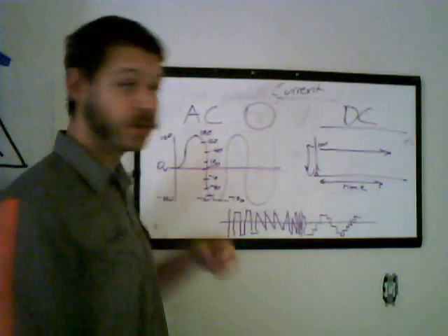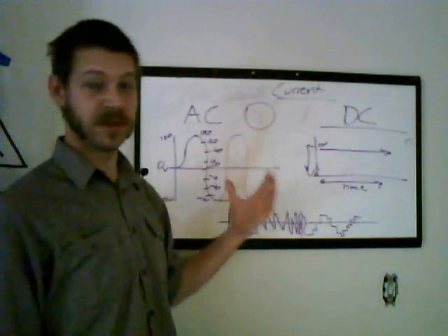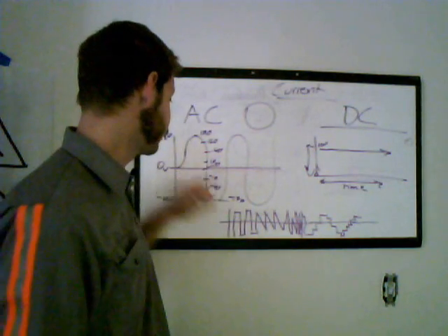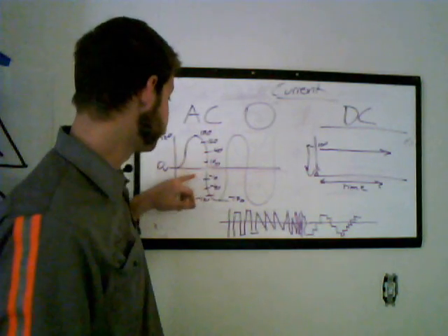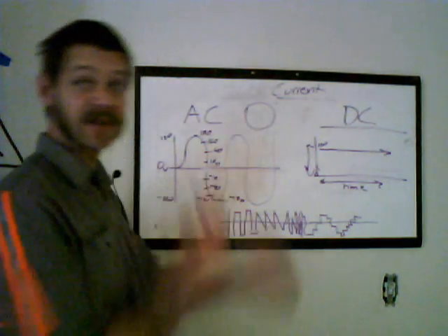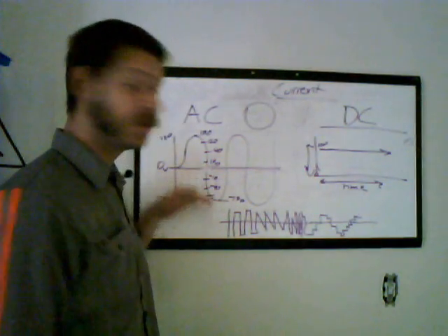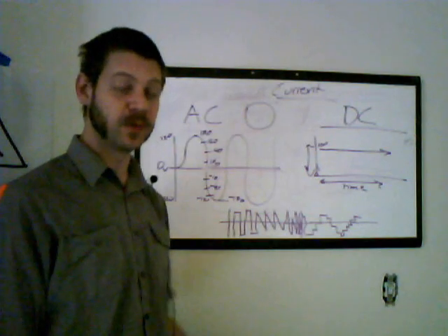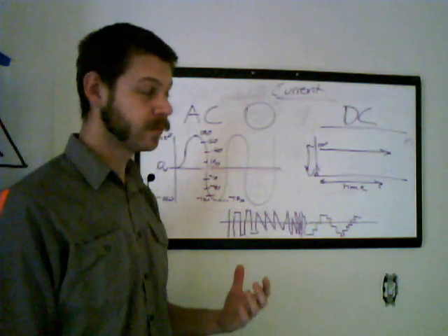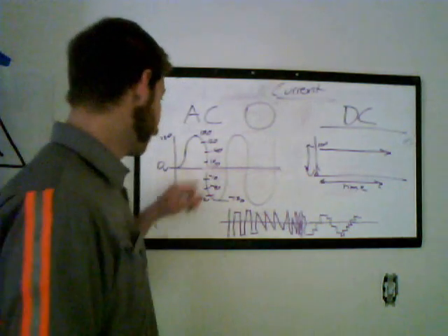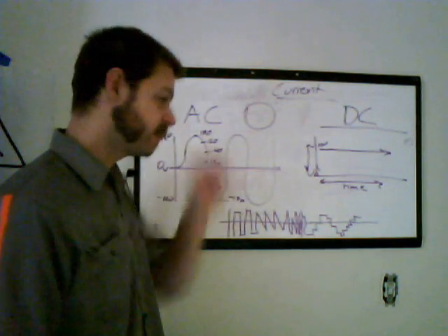Then if you were to measure it instantaneously, even though there was a good deal of current going through it, you would read 0, because at that particular instant, there was 0 voltage. As it passes through the midpoint, it starts producing negative voltage. Negative voltage has the same potential to do work as a positive voltage. So it'll measure negative 10, negative 40, negative 120, negative 170.